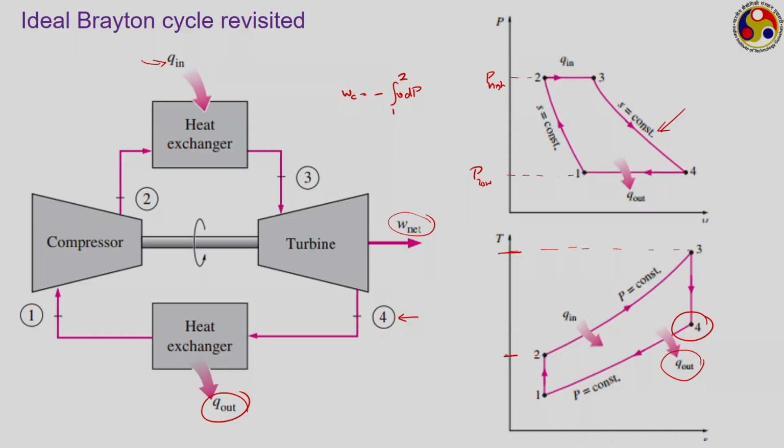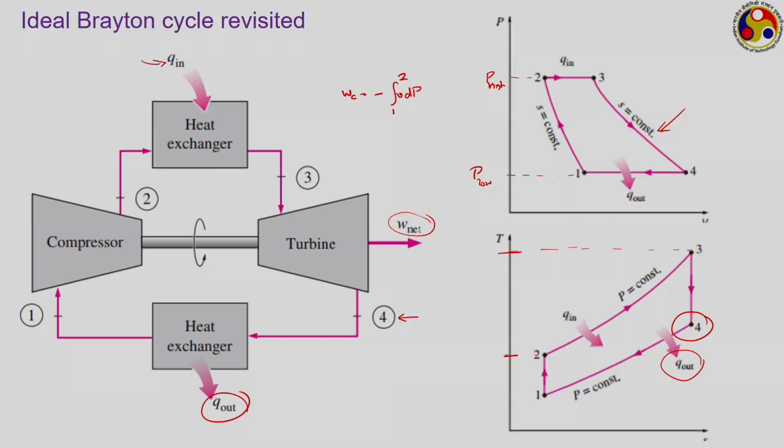Even when you are using the intercooling, the back work ratio can be in the range of 30 to 40%, which is a very significant number. Then what is the way we can reduce this compression work? For a given pressure range, the only possibility is that if we can somehow reduce the specific volume of the working medium. That is precisely what is done by virtue of the intercooling, where we try to cool the gas to a slightly lower temperature, so that its specific volume reduces.